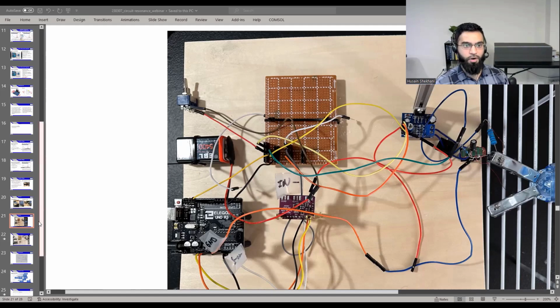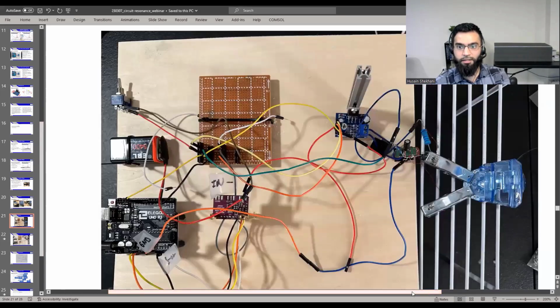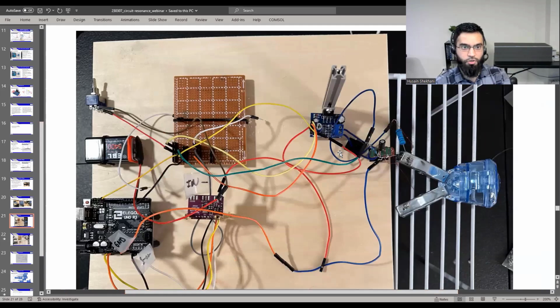So I actually wanted to do the measurement at the transducer. You could also do it at the output here. This is how medical devices do it a lot. They are not allowed to do measurements on the transducer itself because that's connected to the patient, and we don't want the patient to be grounded, right? And we don't want to make a ground loop and shock the patient with a surgical device. So they do all the measurements on the primary side, and the secondary side is isolated completely.